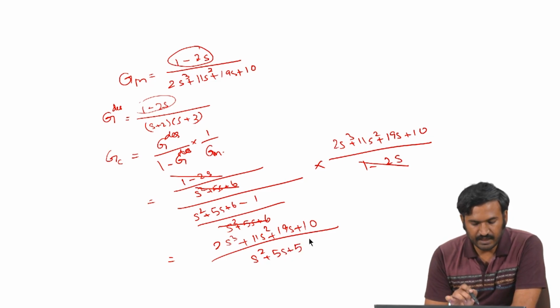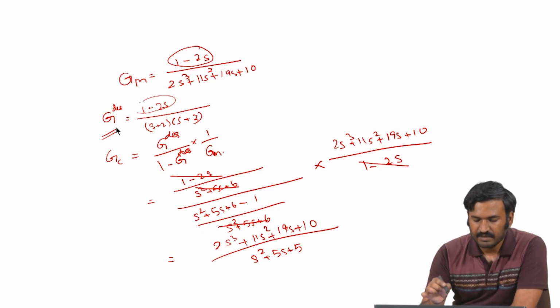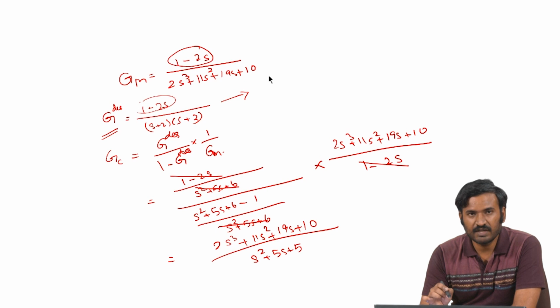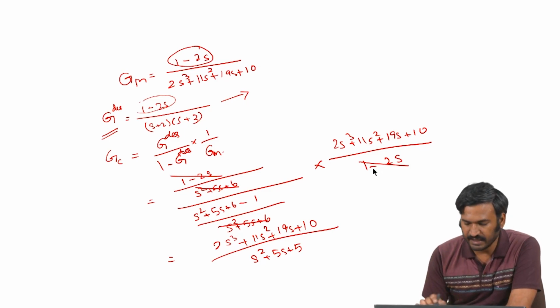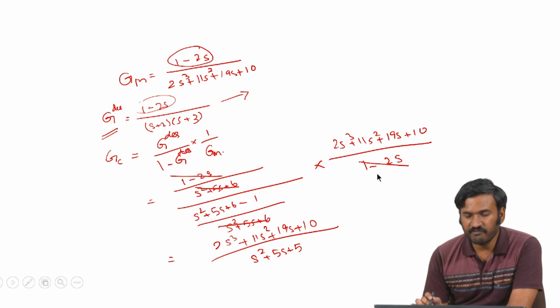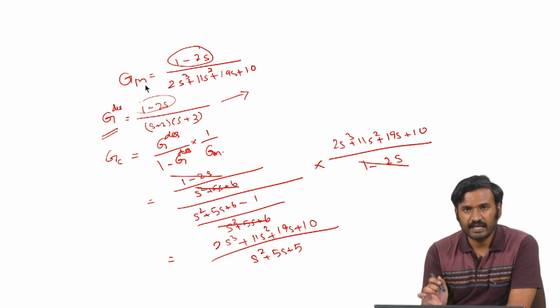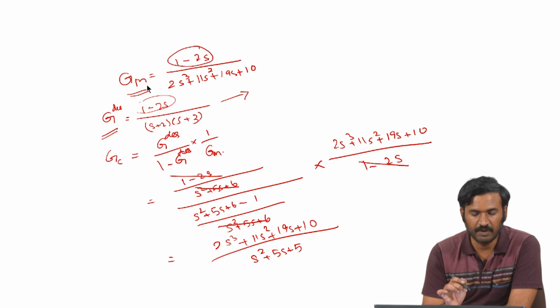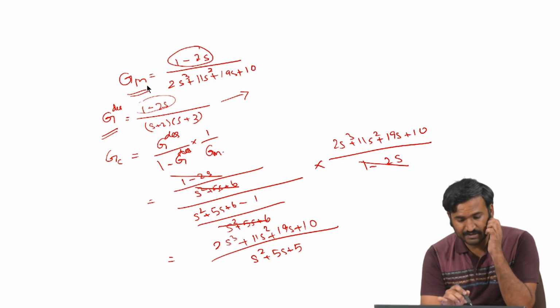Now, we can specify any G desired as we want. So, the main criteria with which we specify G desired is that the gain of the closed loop transfer function has to be close to 1 and the time constant tau of the closed loop transfer function has to be as small as possible. So, remember there is a pole and a zero cancellation here. This introduces a problem when we have GM which is not similar to the process we are implementing the controller on. The process model can change over time. It can also be very different from the model which we have because of some phenomena which we might have missed while modeling. So, due to these reasons we have to look at how this controller will work